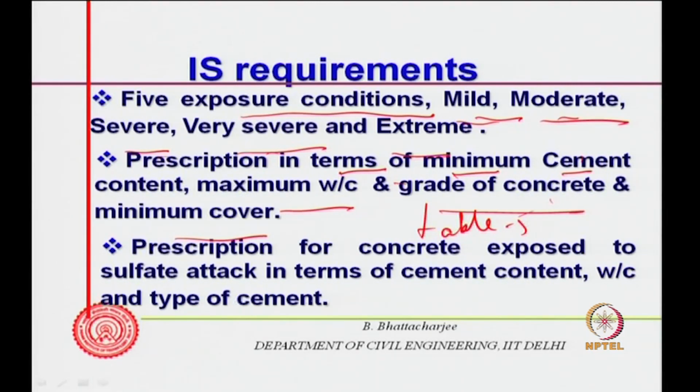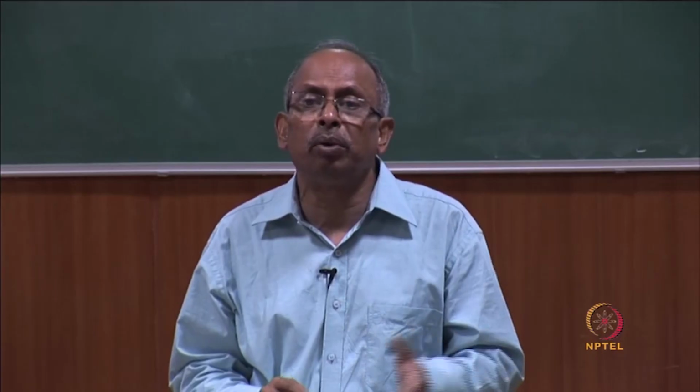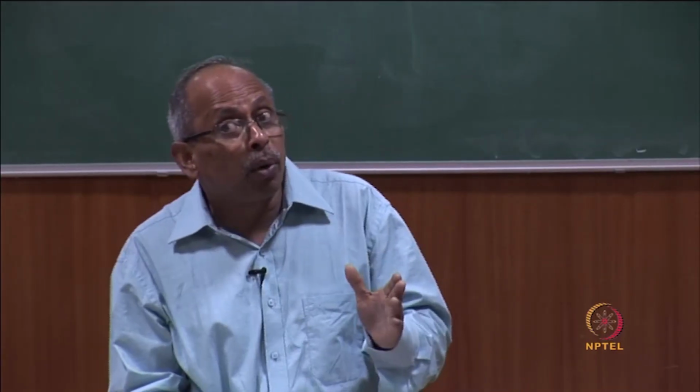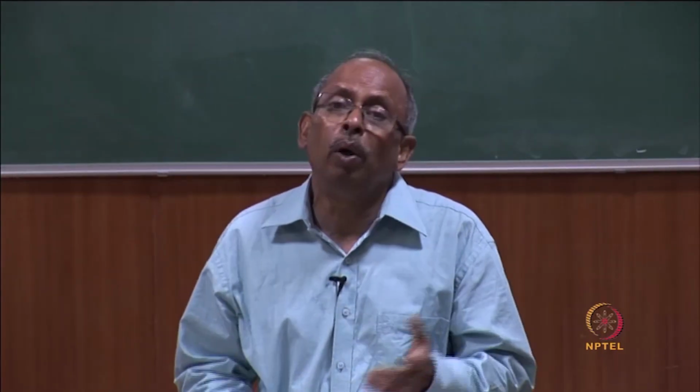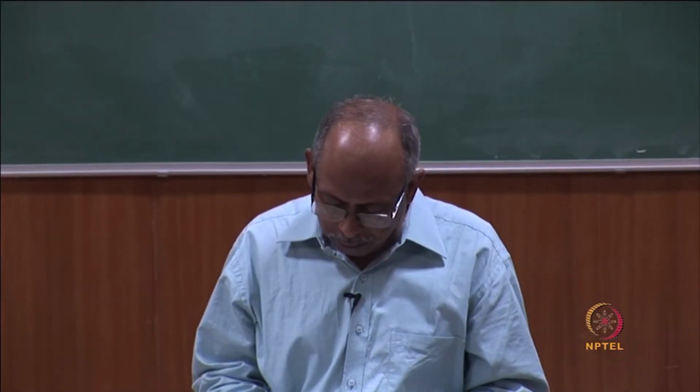Prescription for concrete exposed to sulphate attack, in terms of type of cement and water cement ratio, is also given in separate tables. Certain other tables are there, specific to deterioration, and the maximum chloride content is prescribed. So, all these prescriptions are there. We will look into Table 5 now.